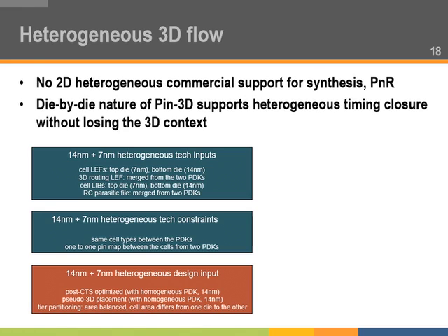The routing structure is created by merging the top die and the bottom die, like the 45 nanometer and 15 nanometer LEFs together with a custom MIV layer to act as an intermediate between them. One requirement here is that each cell in 15 nanometer should have its equivalent in 45 nanometer, and there should be a 1:1 pin mapping between these equivalent cells, so that we can push one cell from one die to the other die without any loss of pin connections.